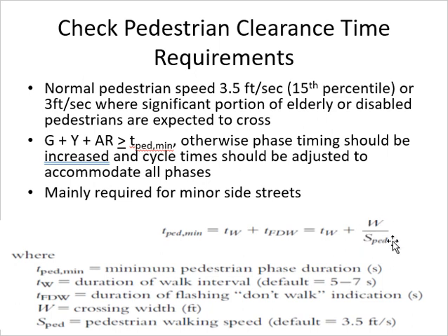When the signal is about to close for the pedestrian, just like we give yellow time to vehicles, the pedestrian yellow time is like the flashing. The signal is about to turn red, so we are warning the pedestrian: move fast now. If you are already on the road or close to the road and want to cross, do it fast. The signal will turn green for the traffic now, so there is very short time for you. We call it flashing don't walk time, and obviously when you see the signal flashing, you walk faster.